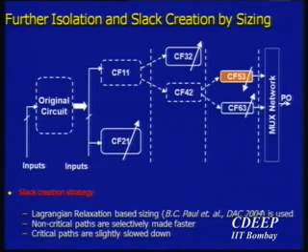Some of you might be familiar with dual VT operations, right? Here, the dual VT operations are going to be, again, a little bit different. The longer paths can have a higher threshold voltage. The shorter paths, or the paths somewhere in the middle, can have lower VT. And again, the really short paths can have a higher VT. So you can get very similar leakage improvements that you'd otherwise get by the sizing methodologies, and the VT assignment methodologies are a little bit different.